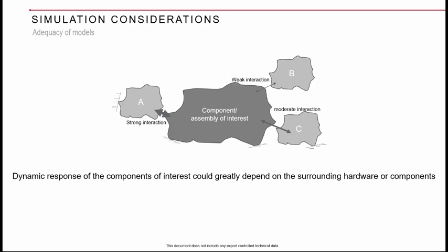the dynamic influence of the surrounding hardware on your component. Whether the component is mounted on brackets is an important thing. If the component is not directly mounted to a boss or rigid structure, but is mounted on brackets, you should definitely consider the effect of the bracket, because with the bracket being flexible, many times people will just say that I will consider an amplification factor for the bracket and apply a modified response onto the system.